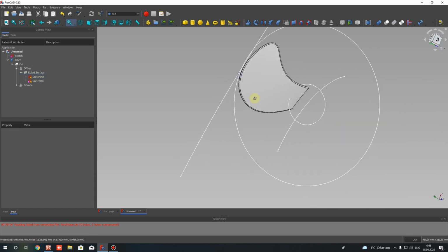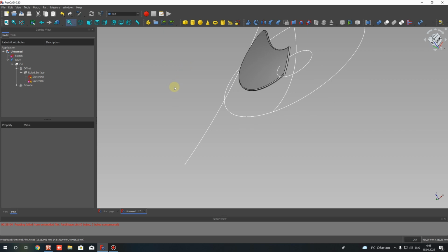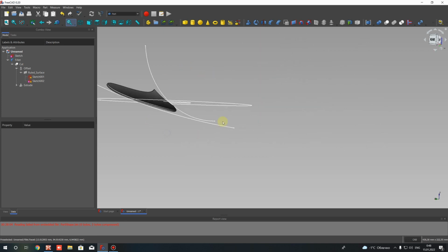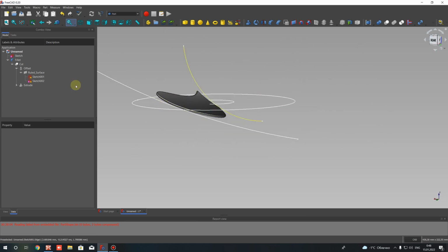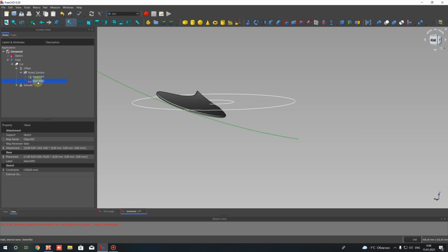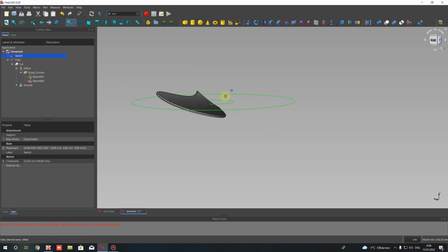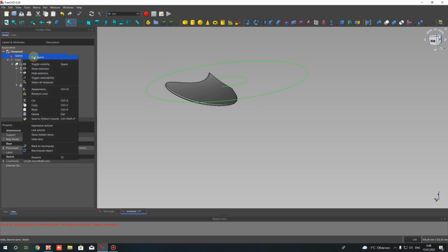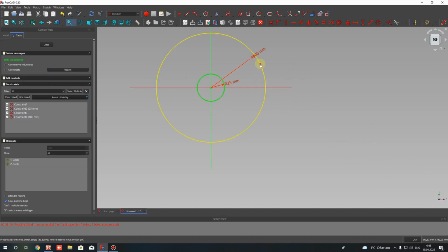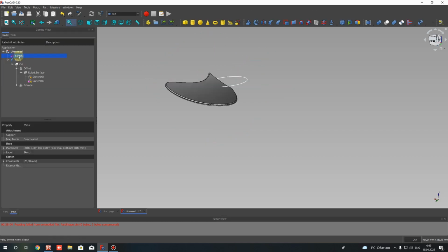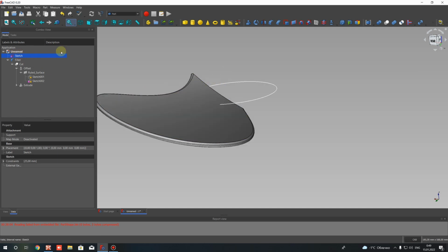after that, when we have set up our blade, let's hide these two sketches and go to this sketch, edit sketch, and we can delete this external radius line, close the sketch, and for this sketch we can create an extrusion.